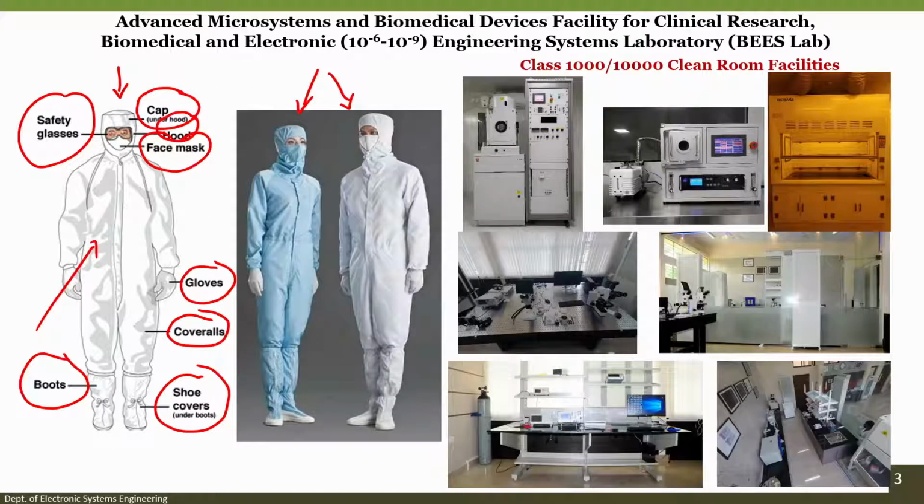In the same way, there are other contaminants on our hands. If I touch the wafer, a silicon wafer, and we will look at what silicon is in the slides, these contaminants from my hand will transfer onto the wafer, and this will kill a lot of chips during fabrication.